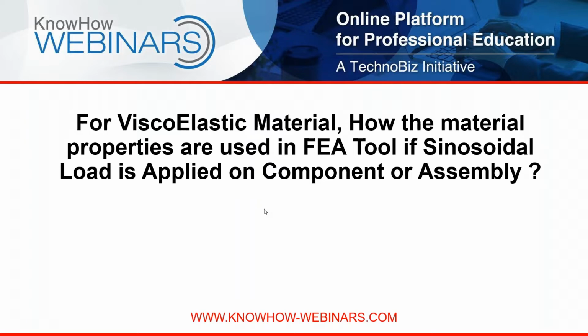The third is the frequency related tabular data that is available in software like Abaqus Standard, by which you can import the loss modulus, the storage modulus, and the tan delta data. All 3 can be input into the FEA software.